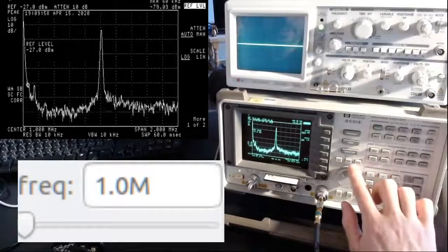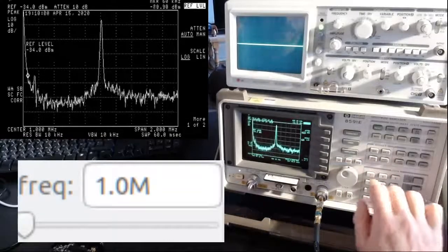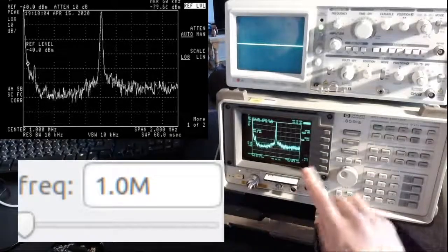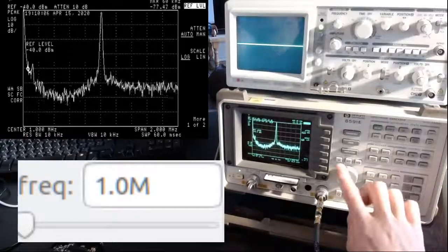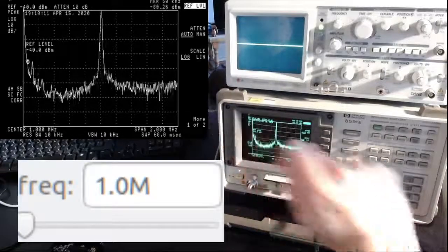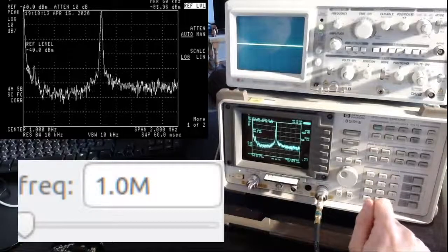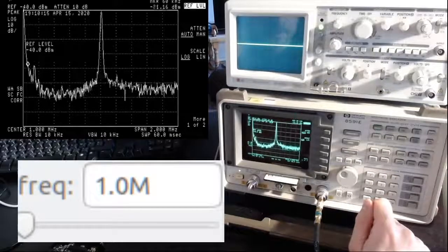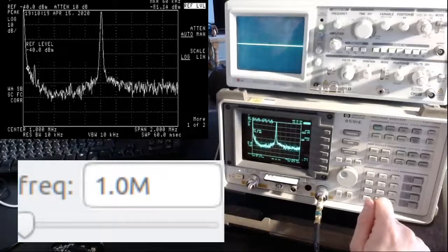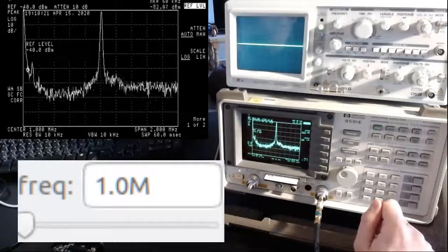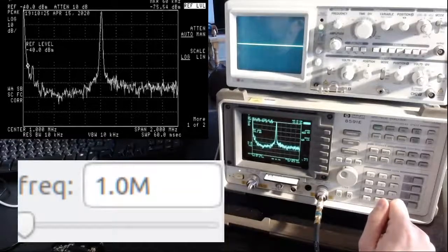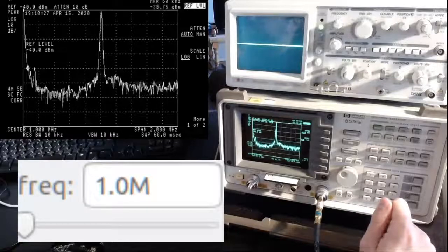So this is what you get. You see also this sort of asymmetric response here, where the right part is kind of having more energy than the left part. I don't know. So I would just say that the HackRF is not good at all at outputting at these frequencies, or at the very least, you have to use a filter after the output to clean the signal.